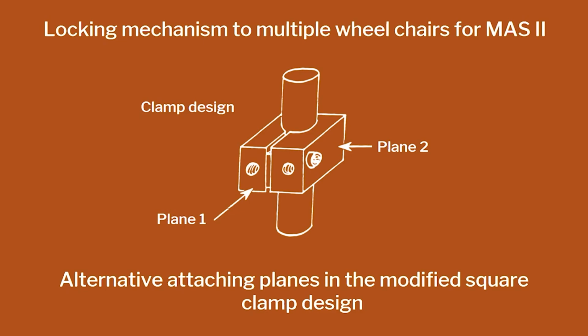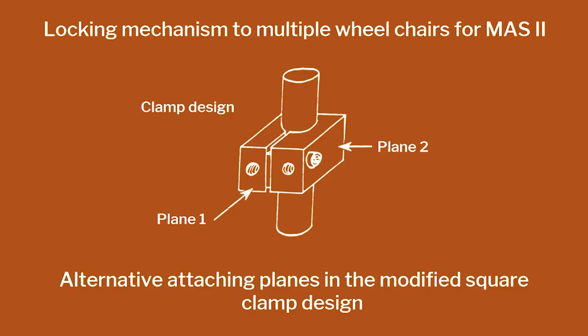Originally we put the two screws here because it was a circular object, and in that circular object the end of the cylinder was the only plane available. But it's a rectangular object. I have more planes. I can put my bracket here. Therefore this whole struggle that we are going through of making sure that these two planes have to be on the same plane can now be dispelled with. If I do that, I don't need these two screws.